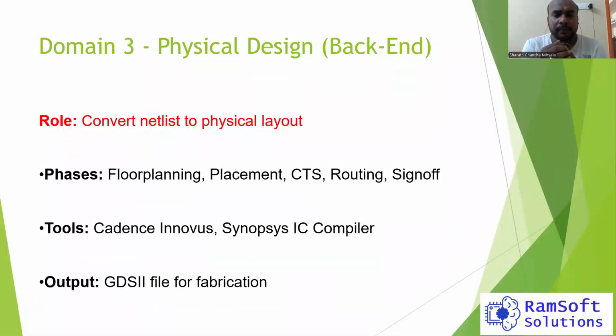In this step, you will convert the netlist that the RTL team has given, which is verified by the DV team, and came to the PD team. You are in the PD team now. Your task is to convert this gate level netlist into a physical layout.